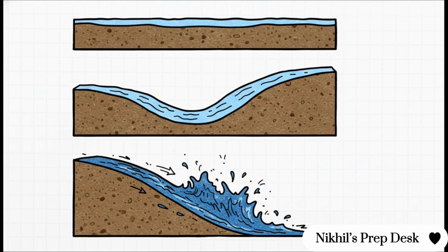When those assumptions are actually met, the law guarantees some incredibly predictable properties. First, a zero-pressure gradient guarantees no flow. We call that a hydrostatic condition. Second, if there is a pressure gradient, the flow perfectly tracks from high pressure to low pressure. And mathematically speaking, a steeper or greater pressure gradient will always result in a much faster discharge rate. Basically, because of these strict assumptions, groundwater predictably follows the path of least resistance and the highest pressure drop.